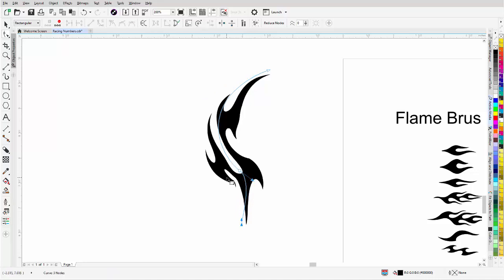Now when you see unsmooth areas in the brushes, that's usually because one of the nodes is causing a problem. Since you're in the shape tool, you can hover over. Now you see the cursor change to the squiggly shape, double click, drop a node there, come here, double click, delete the node, come here, get the control arm and the control handle and make it change that, and you can see how that's changing the shape of the brush.